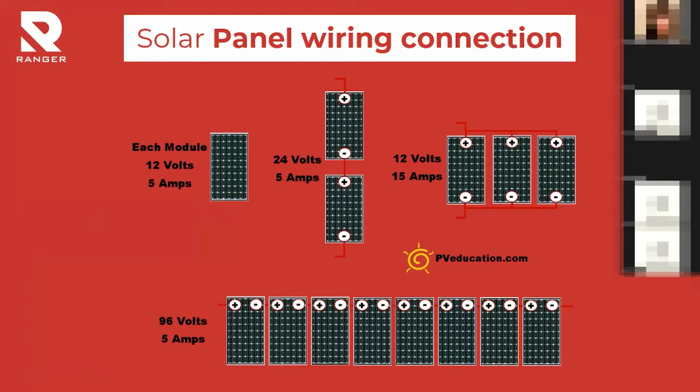When the panels are connected in series, the output voltage is added together and the output current remains the same. When the solar panels are connected in parallel, the output voltage remains the same and the output current will be added together. As you can see from this diagram below, connected by series, so the voltage is added together.